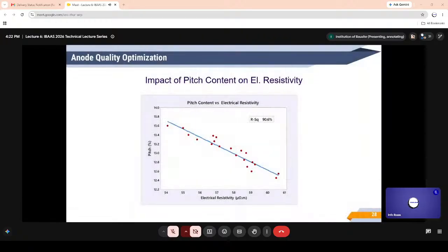Coal tar pitch has relatively low sulfur content in the range of 0.5 to 0.8%. It is converted to pitch coke during anode baking. The pitch coke is pure, has low sulfur content and elemental impurities. With the increase in pitch addition, the quantity of coke with low sulfur content increases in anodes. There is an overall reduction in the sulfur content of anodes.